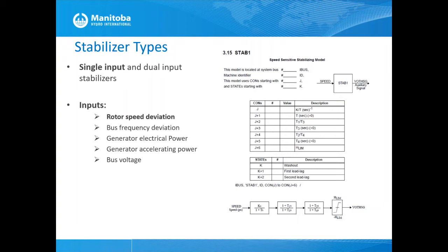This is important when there are exciters with very large gains, but you have to carefully select the values for the stabilizer output, and that can be done through trial and error time domain simulations. So the goal here is to find parameters for these, which I have marked here, and let's see how we can do that.